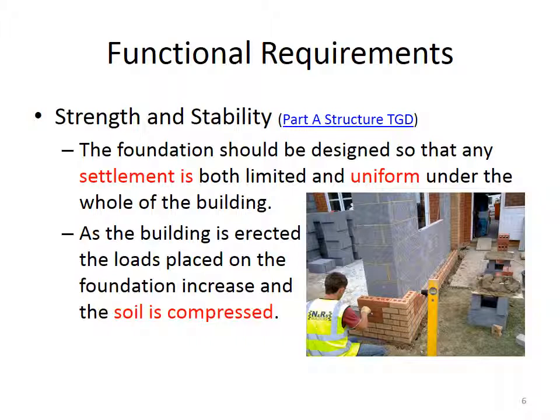So if the building is settling, we want the whole building to settle at the exact same rate and the exact same amount. In other words, we don't want one section of the building settling more than the other. Then we're going to get cracks in the building. As the building is erected, the loads placed on the foundation increase and the soil is compressed. So it's important that we dig down until we get to good solid ground.